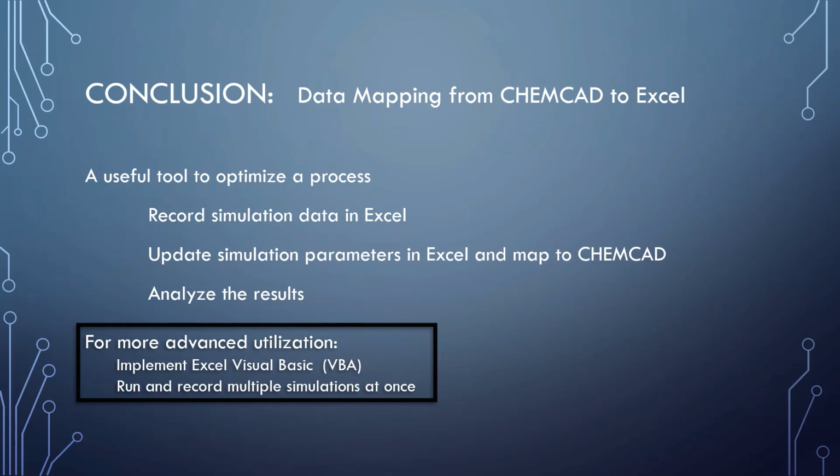Something to make this even more useful is to implement Excel VBA, so you don't have to copy and paste one simulation's data over so it's not rewritten in Excel. You can implement VBA, Visual Basic, and run and record multiple simulations at once, and that's what makes this tool really powerful. So I recommend you learn that next if you haven't learned it already.